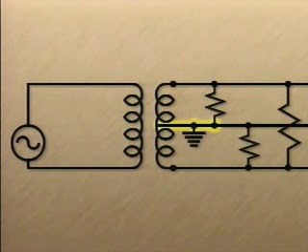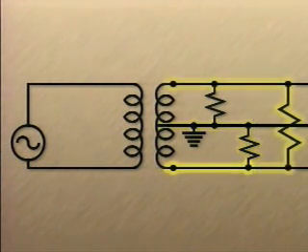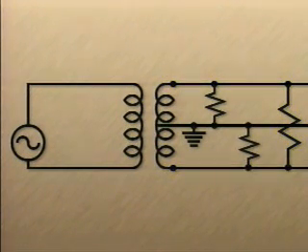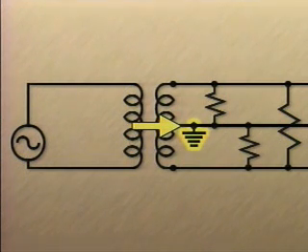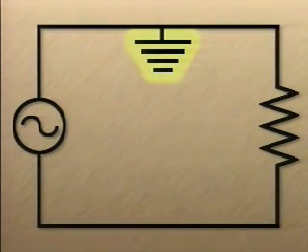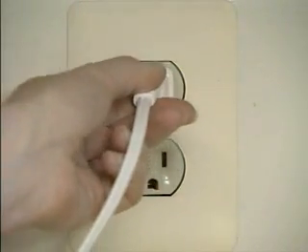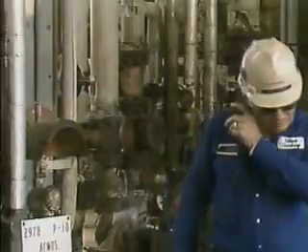The voltage between the neutral line and either the top line or the bottom line is 120 volts. The voltage between the top line and the bottom line is 240 volts. So it is possible to get either 120 volts or 240 volts from this three-wire single-phase system. The neutral line in a three-wire system is usually grounded as a protective measure. The same is usually true for one of the lines in a two-wire system. Then, if an ungrounded line accidentally becomes grounded, a short circuit will occur, and the circuit's fuses or circuit breakers will open the circuit.